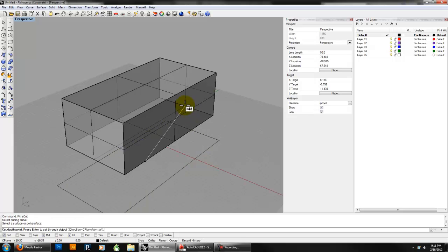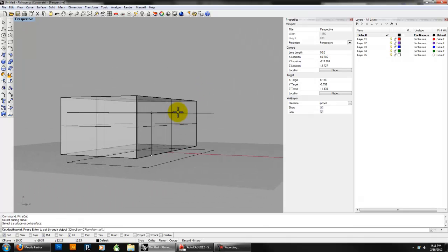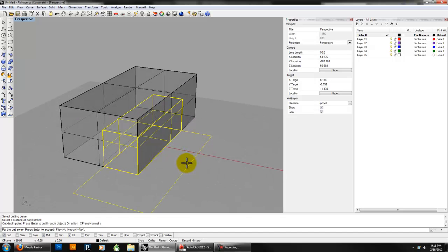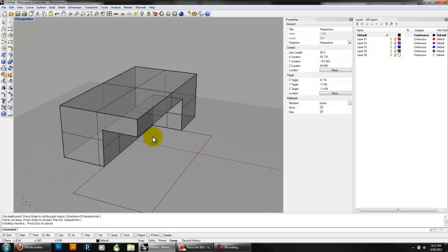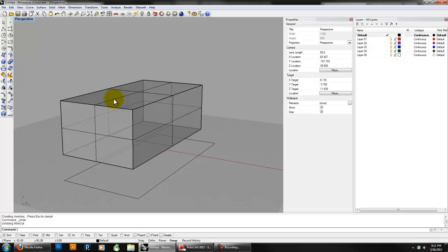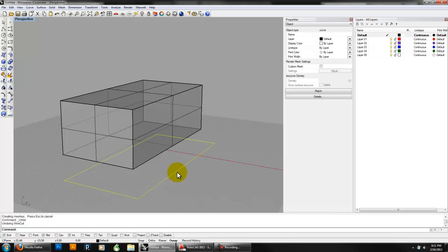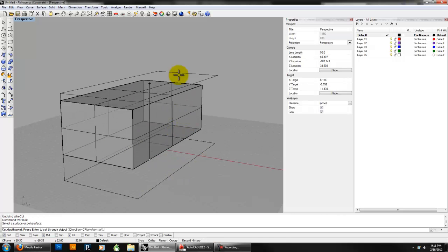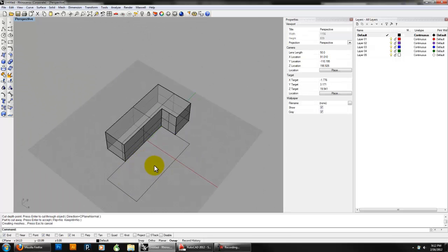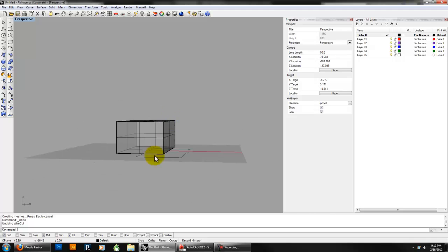And the surface is your object, and you can pull this through at a certain depth, and then it says part to cut away, and you just cut out the piece of something. So it works kind of like a Boolean, but you can do it with a section of something. And you can wire cut all the way through as well. You could use this to cut away the top or bottom or something.